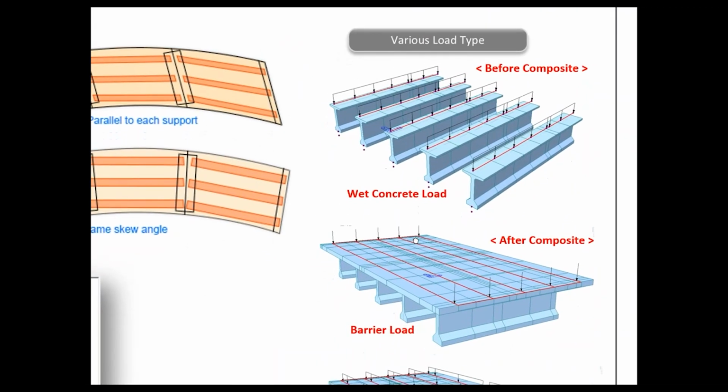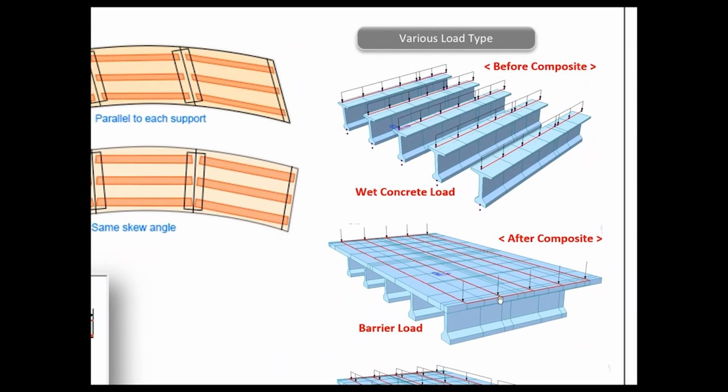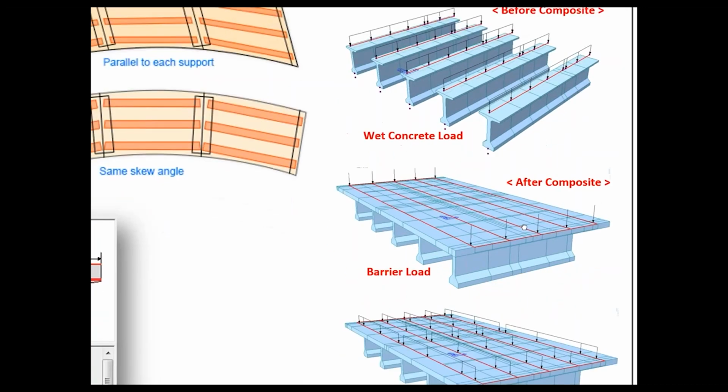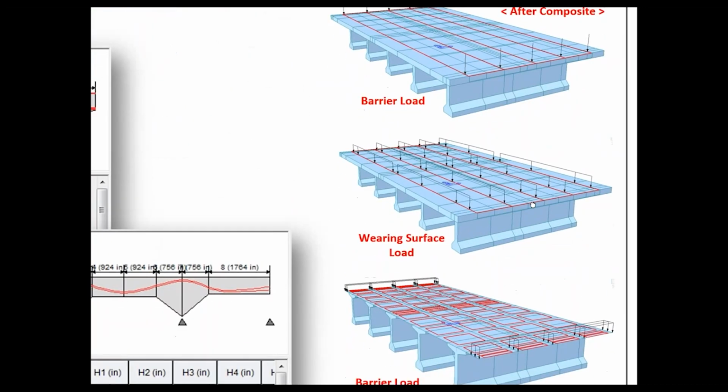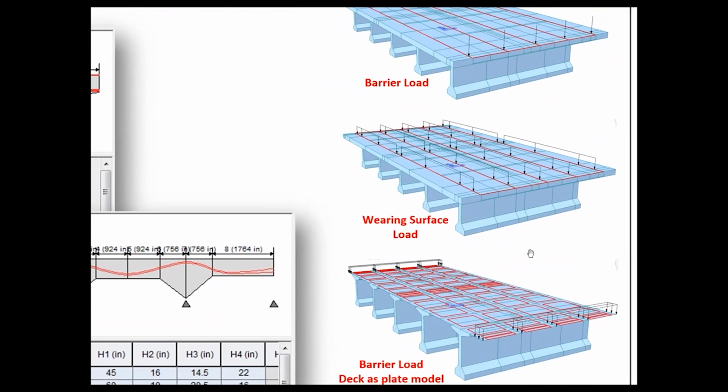And when you define your loadings, dead load, and various superimposed dead load, it's going to apply them in the most proper format like this. So if you, within Civil or in any other program, were ever curious, like, oh, I punched in this loading, but how is it being applied? You can actually visualize it within your model of Midas Civil, just like this.